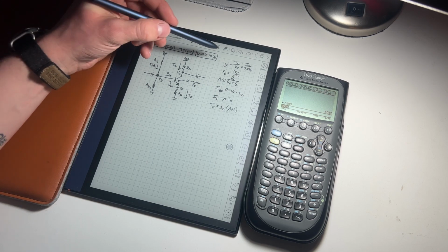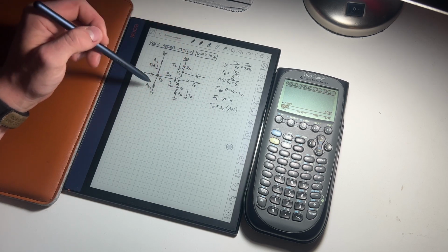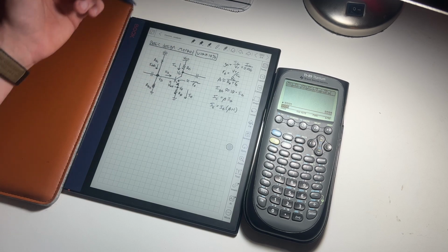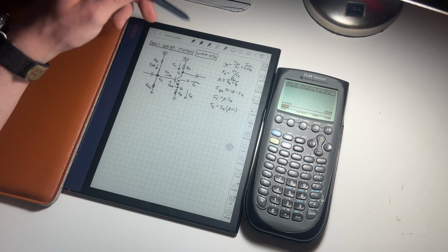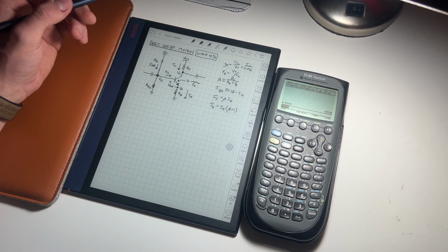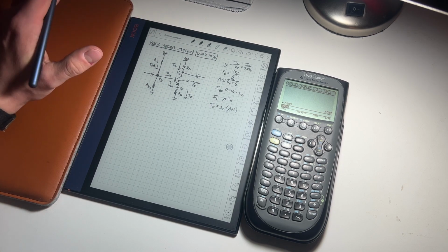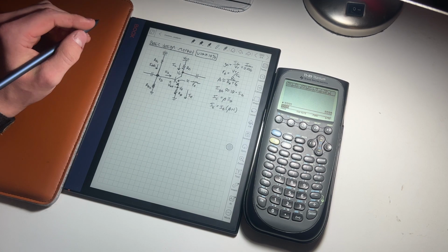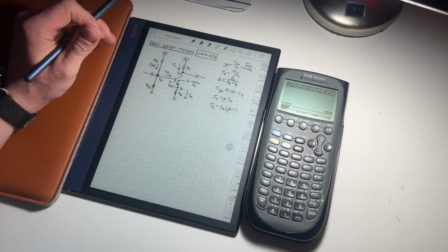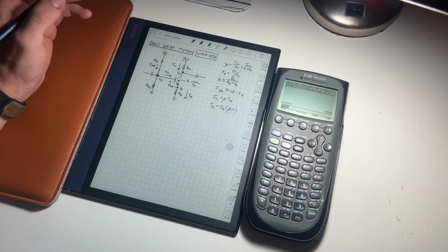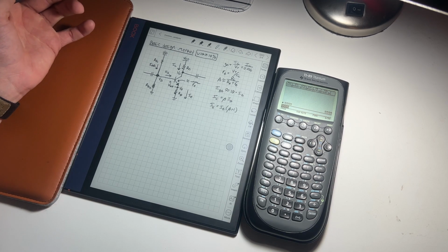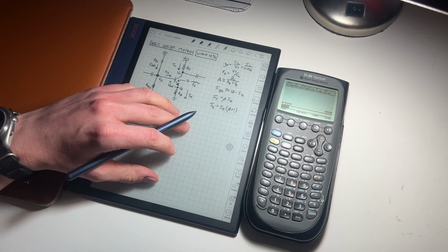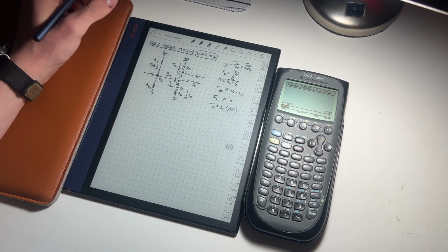So I have a couple equations written down here and then a bunch of circuitry stuff going on here, and I'm going to dive into these first, and then we'll go into the step-by-step process that I made. It's about 8 steps on how to accurately design one of these for the specific gain. And then later on in the video I'll go into LTSpice and simulate an example circuit that we're going to work out here, and we'll see how the gain checks out.